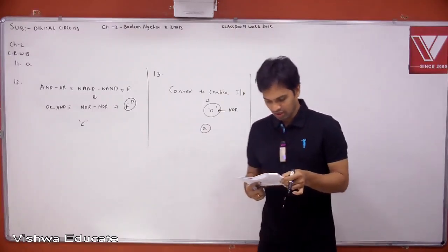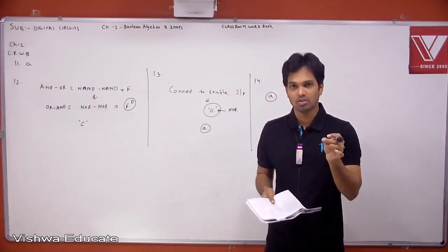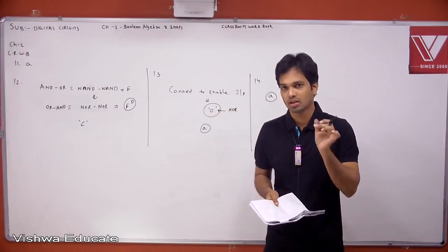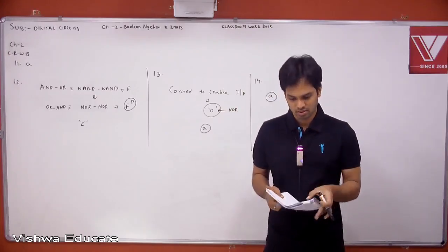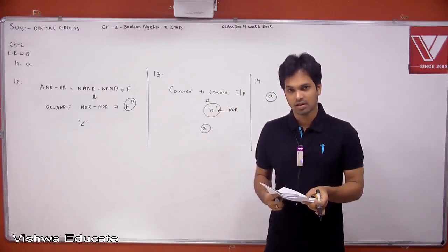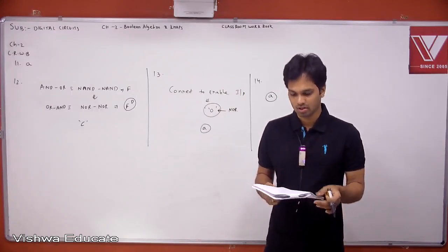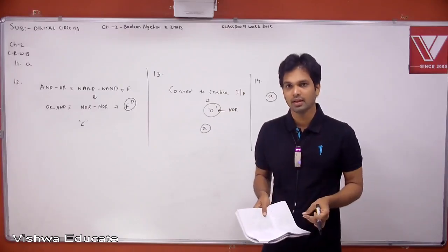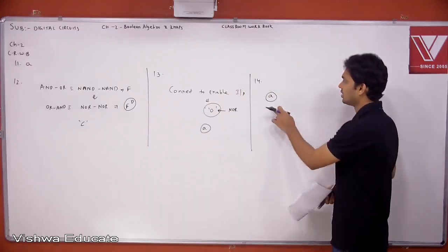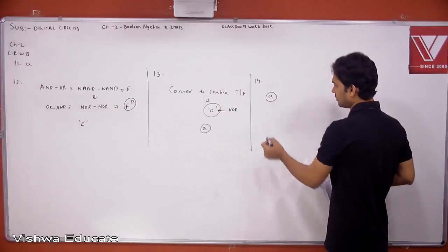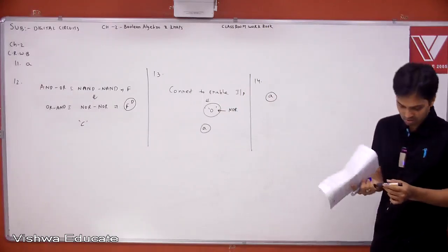Static 0 will occur in AND OR. No, in a properly formed AND OR logic, there is no static 0 hazard, we discussed in the class. Next, dynamic hazard, it occurs in multi-level combinational circuits. Essential hazard occurs in sequential circuits. So what is the answer? Option A. Static 1 hazard will occur in AND OR. Now let us see question number 15.